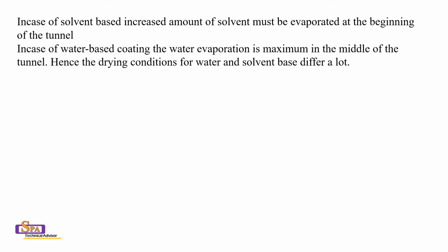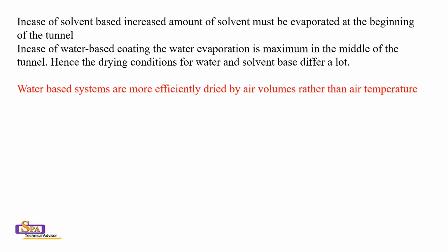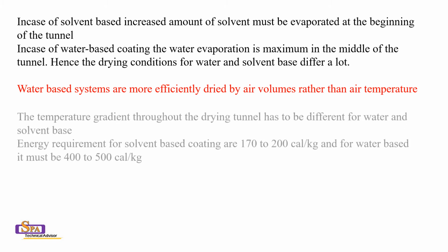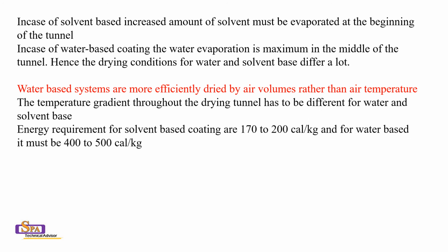Hence, the drying conditions for water and solvent base differ a lot. Water-based systems are more efficiently dried by air volumes rather than air temperature.